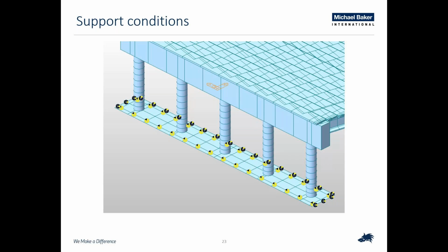That are great tools to use. But yeah, we had taken out and isolated just one of the abutments or bents with the columns, and used the plastic hinging properties from that general section designer right into that MIDAS model. But anyway,